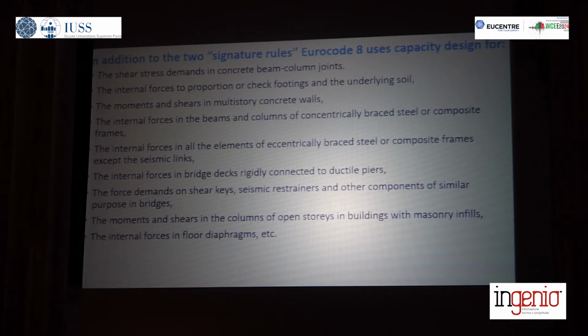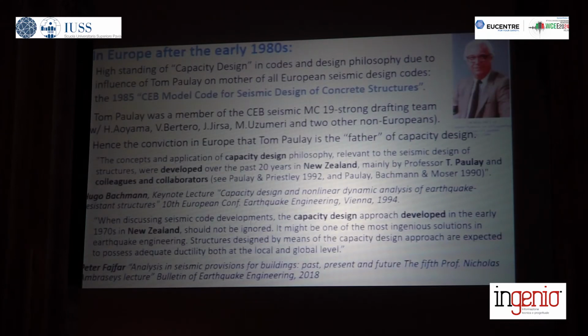Also, the bridge decks connected to ductile piers or other elements of bridges which are required to stay elastic, as well as columns of open stories in partially infilled buildings and floor diaphragms are all designed with capacity design, the capacity design approach.